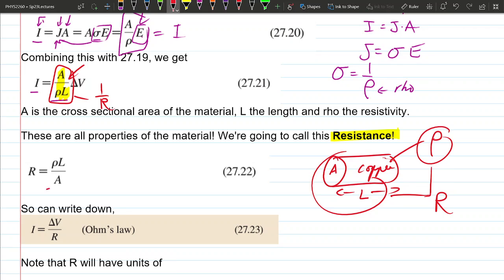So therefore, resistance is actually the resistivity multiplied by the length of your conductor, divided by the cross-sectional area. Let me go back to this cable multiple times. This particular cable is made of, let's just say it's copper. It's probably not, it's some sort of alloy. By knowing it's made of copper, I instantly know what the resistivity is.